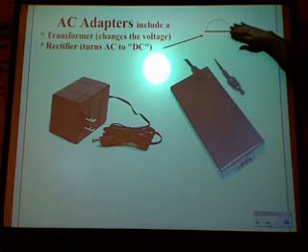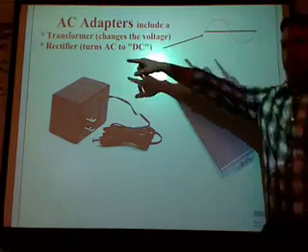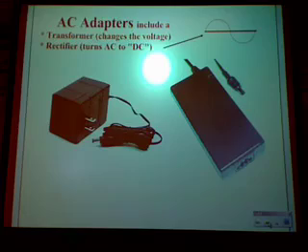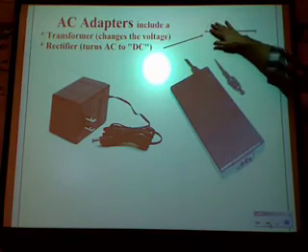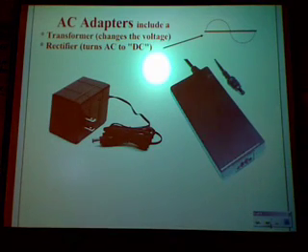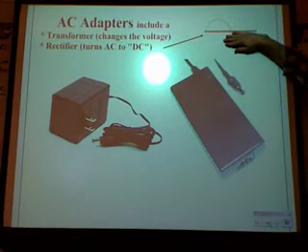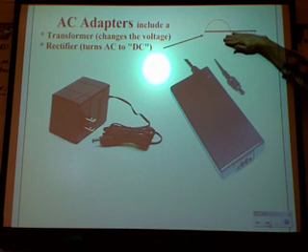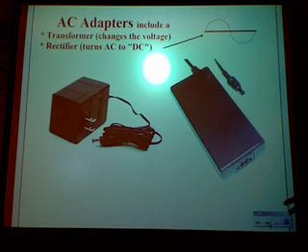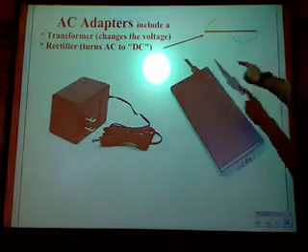We can't have this. So there's a device called a rectifier. To rectify means to fix or to change. And this rectifier is going to change this AC into kind of sort of like DC. We need to get rid of this part. And there's a simple way to just chop off anything that goes negative. We'll talk about that device later on when we get to this part down here. But it's called a diode. If we use 4 of those devices together, we make something called a rectifier.